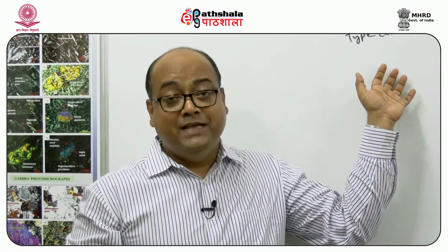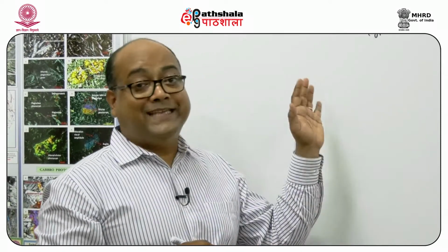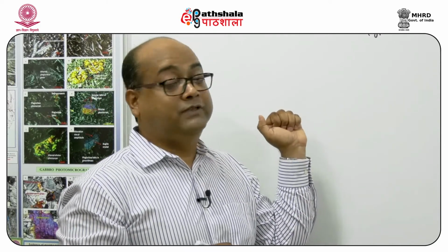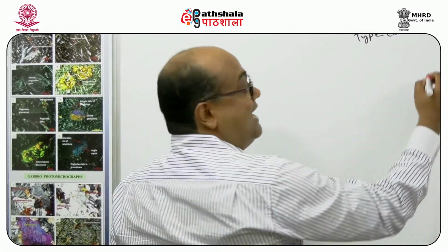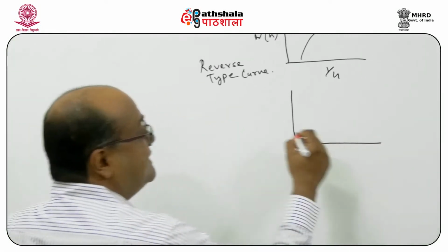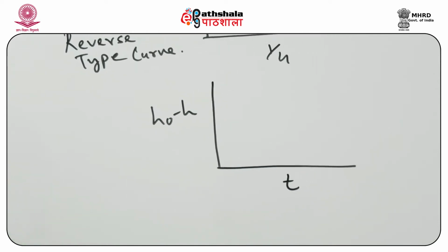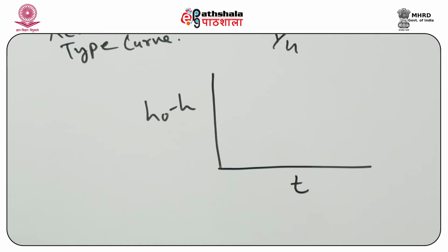Now, how is this curve used in the graphical solution? What we measure in the field, remember, is drawdown only. So the graphical solution given by Theis is that we measure drawdown in the field with time. In a very similar manner, we are measuring H0 minus H, and time is on the x-axis. Again, these two variables are also plotted on a logarithmic scale.